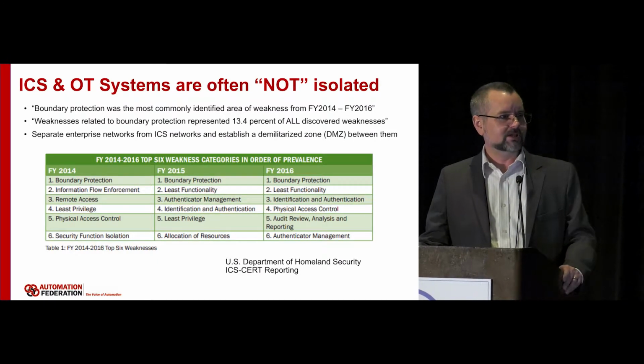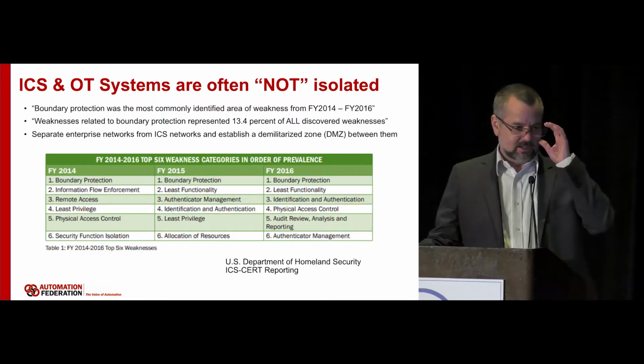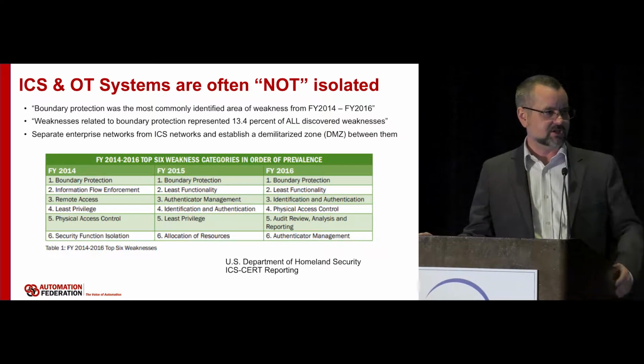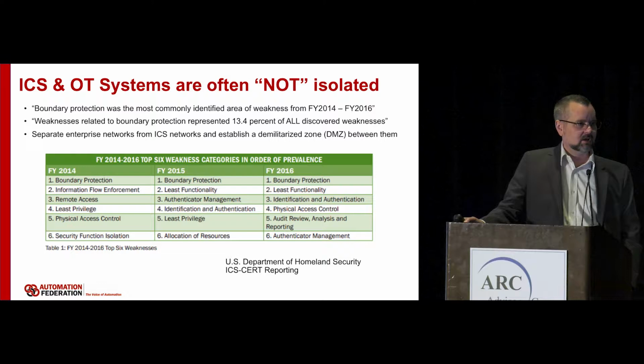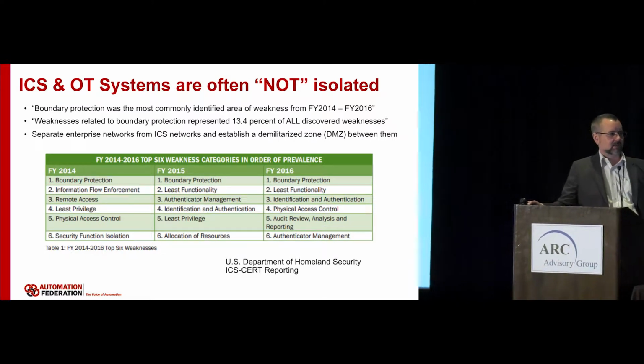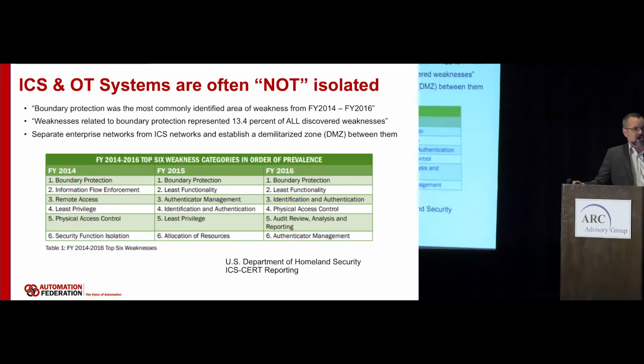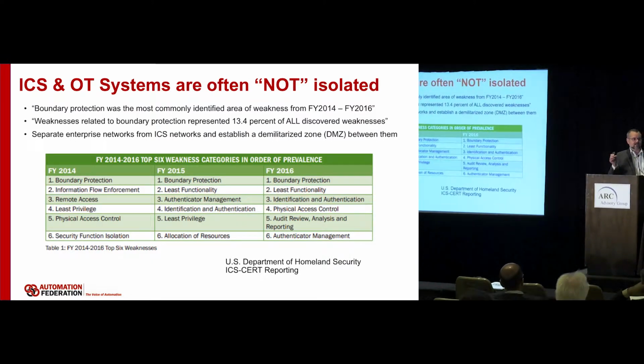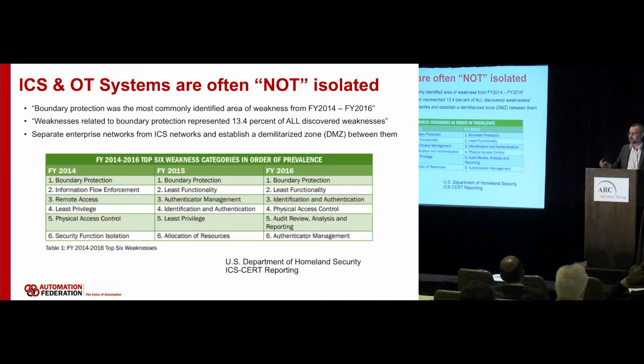There are some really interesting exfiltration techniques that go on. I watched a presentation at S4 earlier that was talking about changing the logic inside the PLC to make the RF signature of that PLC change, so that you could, at a distance, point an antenna at it and basically send the equivalent of Morse code.